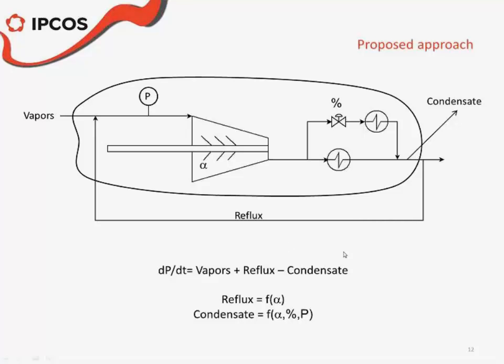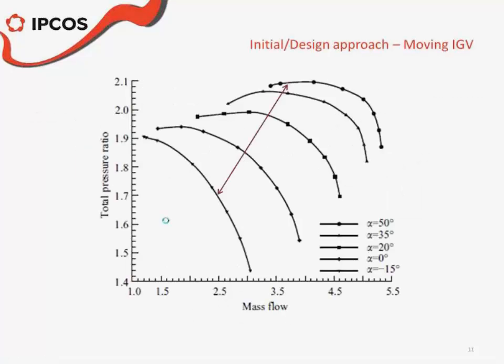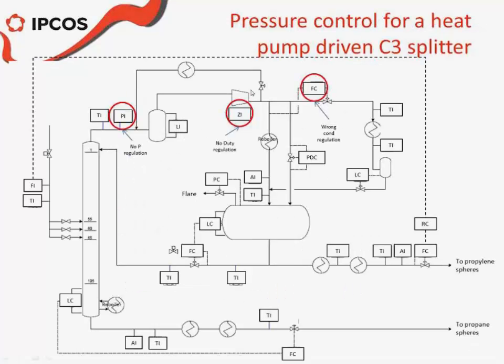So what we did was look at the whole picture, and not only the little part in which only the compressor and the vapors are considered, and we extended the envelope to also consider the condensate part. Let's go back a bit to the drawing. If you see here, the vapors are split into two. One part, the biggest part, is going through the reboiler, but there's a small part that you can actually regulate, which goes through a cooling water condenser, an auxiliary condenser.